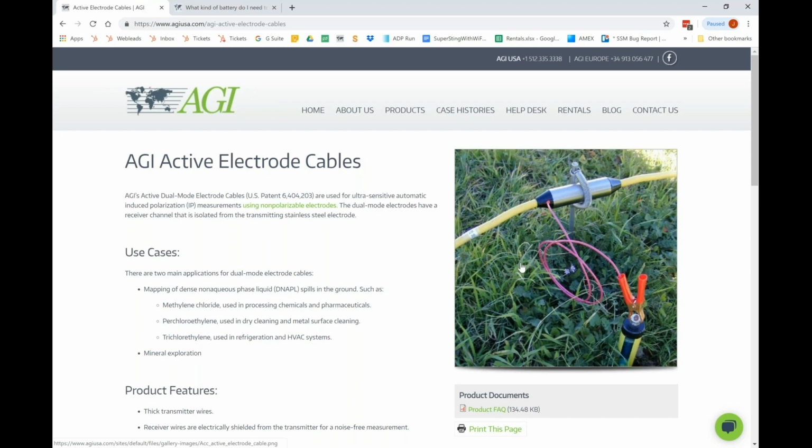There are some cases where you only use half your passive electrodes, like if you have a switch box 56 and you want to run 28, you can put the low address port on the switch box at either end of that cable. It doesn't matter. There are some cases where a connector is damaged and you may want to move to the other end of the cable to avoid that particular connector. But those are all site-specific troubleshooting issues.